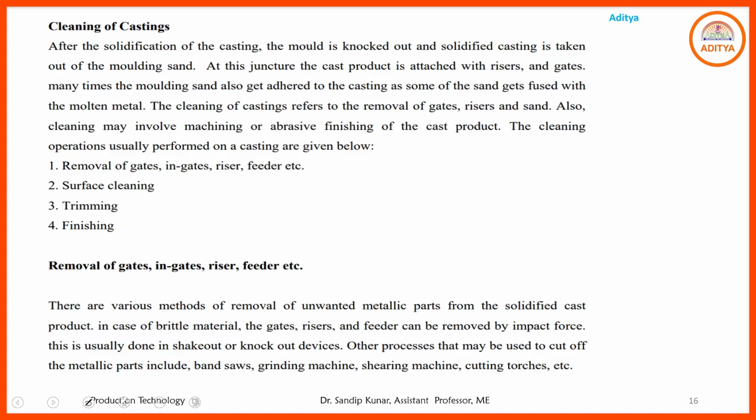So in that case, we take it from the molding box, then we use air blasting or water blasting. First we remove some debris from that particular casting product. Then sometimes extra burrs or extra depressions, some wire tears may happen on that particular product.